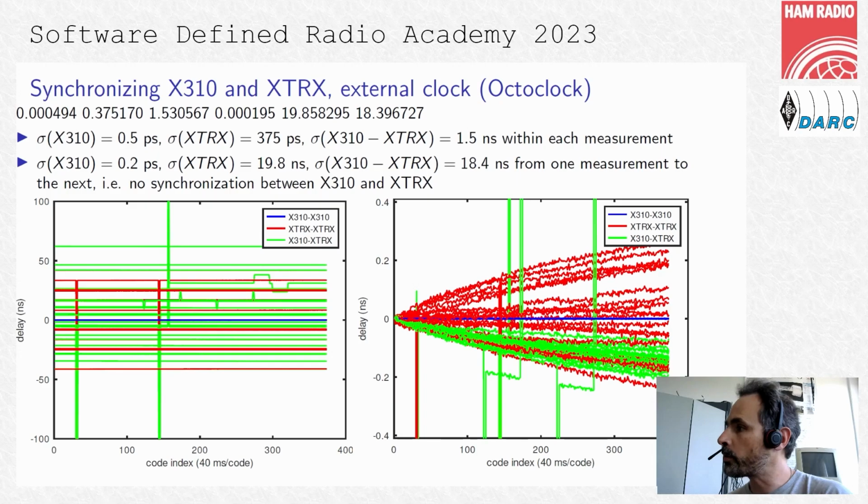I have no idea what's inside an LMS7002. I have no idea how Lime Microsystems architected the receivers, but you do see that the samples are drifting between the two A to D converters, which is not happening on the Analog Devices hardware and is not obviously happening with the FPGA sampling the data. So something here is shaky with the XTRX LMS7002 that needs to be investigated.